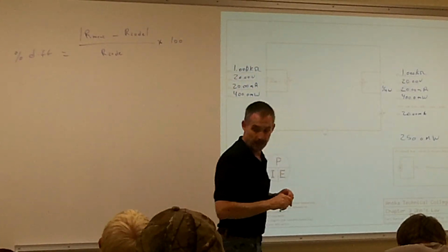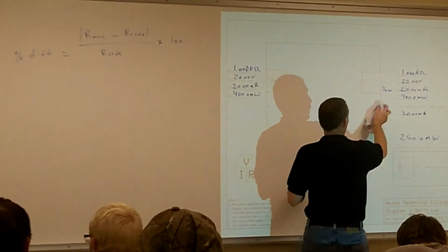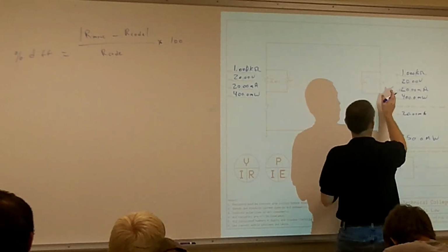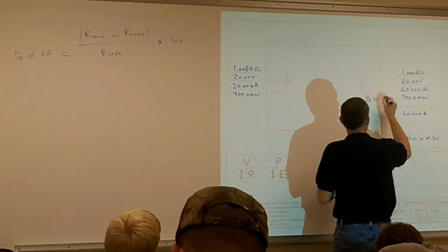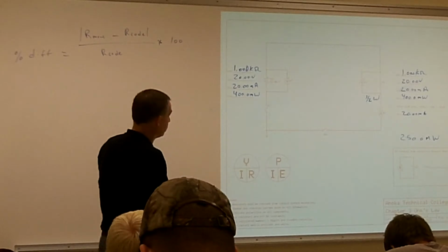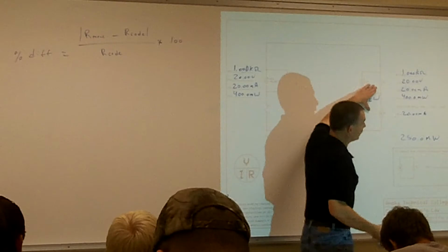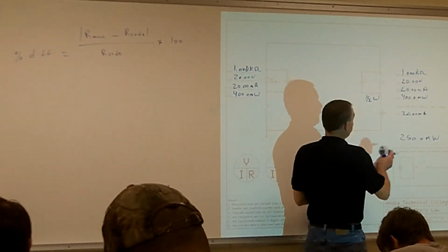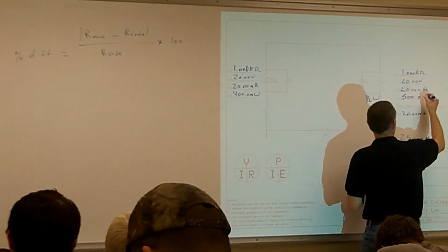So we have to jump up to what size wattage resistor? Half watt. It goes from 1/8, quarter, half, 1, 2, 5. So it jumps up. So you want to make sure that this thing was a half a watt. You don't want to go to a 1 watt because it's going to get a lot bigger. It's going to take up a lot more real estate on your board. Plus, they're going to be a little bit more expensive. So you want to rate them appropriately. Now, if this thing was, let's just say, for example, at 500 milliwatts.